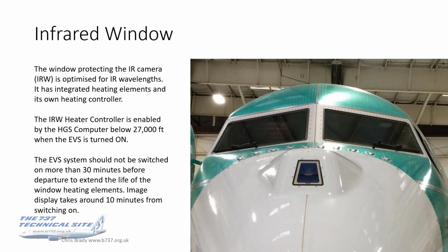Just like any anti-ice system, I suppose. And the guidance from the manufacturers is that the EVS system should not be switched on more than 30 minutes before departure to extend the life of the window heating elements. Yep. Now, image display takes around 10 minutes from switching on, so I guess you've got to time it as being between 10 and 30 minutes before departure.